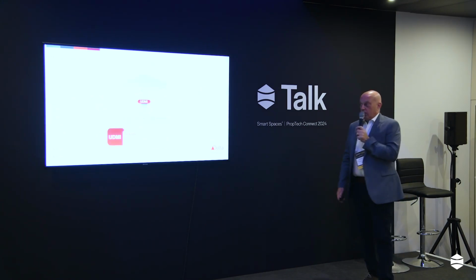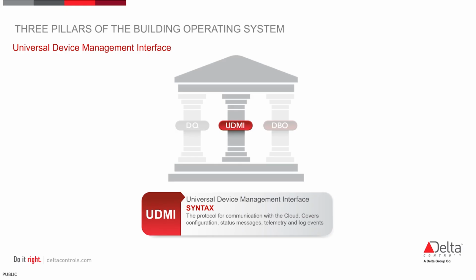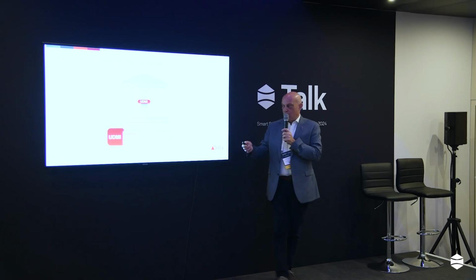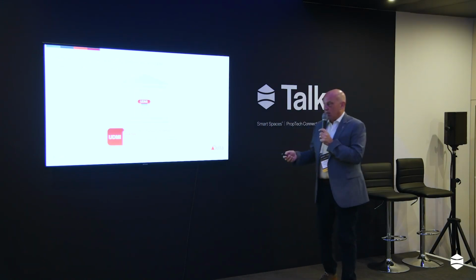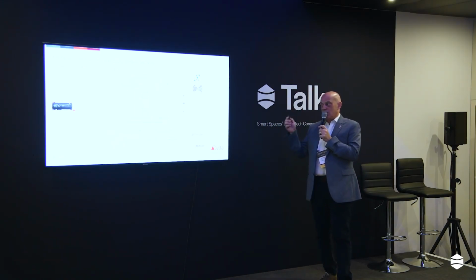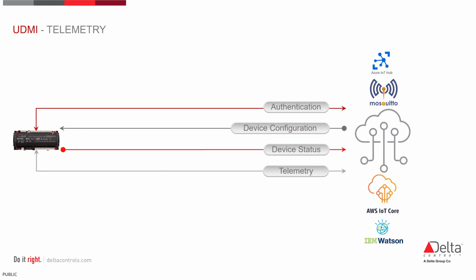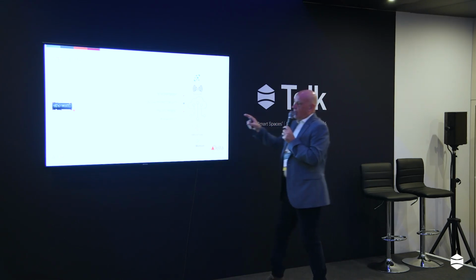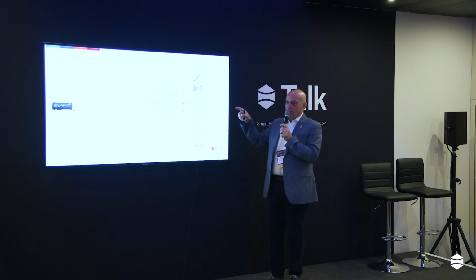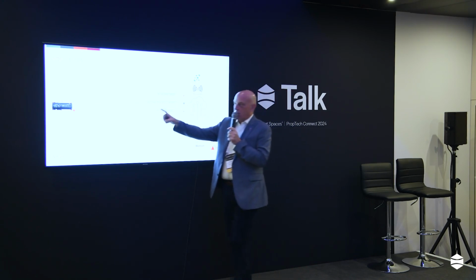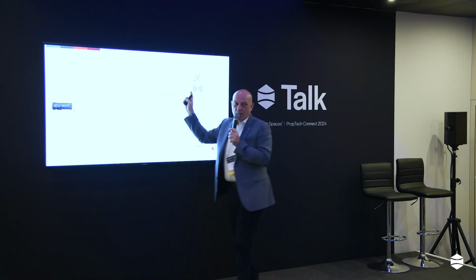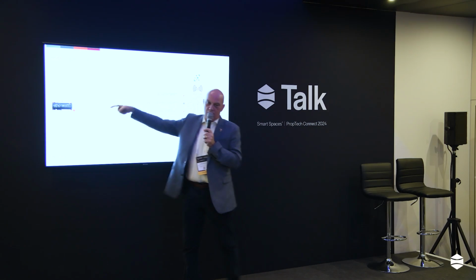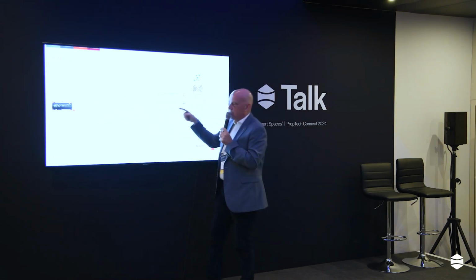Next stage would be UDMI, Universal Device Management Interface. So this is the language that is defined to push the data into the cloud data lake to make things work. And it's really the difference between this being a management interface rather than just a method of taking a piece of data from a building and putting it into the cloud. So that means various things. One of which means that not only does the device send data into the cloud, it can also have data pushed back down into it to change settings, to adjust set points.